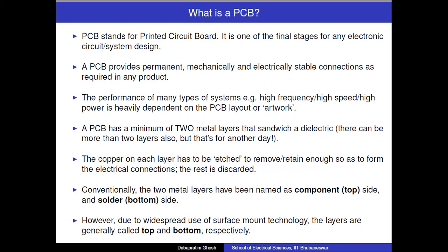If you are going to use breadboards and wires, they would not last. So any wire could come off very easily. So a circuit board, a printed circuit board is not like that. So the way this PCB is designed, or rather how the connections are printed, how the components are arranged and kept on the PCB, they may have a lot of role to play, especially at high frequency applications or high speed applications, or especially which might be a point of interest for electrical engineers, high power applications.